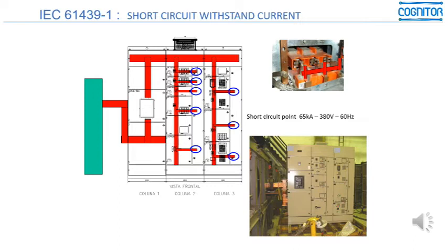We have also, in another part of this short circuit test, the verification of the ability of the circuit breakers to interrupt the short circuit without letting it pass for a long time. Let's say you applied a short circuit, but in this case, instead of leaving the current to circulate, for example, for 1 second, the circuit breaker will open the circuit. You are checking then the circuit breakers.